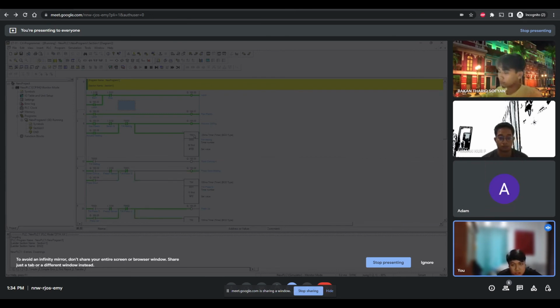As you can see, once the plastic has been inputted into the melting process, there's a certain timer here. Here we have set it to 10 seconds for the plastic resin to melt completely. After the plastic has been melted, it will be transported through a motor conveyor. With the motor conveyor, it will turn on the pressing sensor. Here, the melted plastic will go through a conveyor and it will enter a mold.